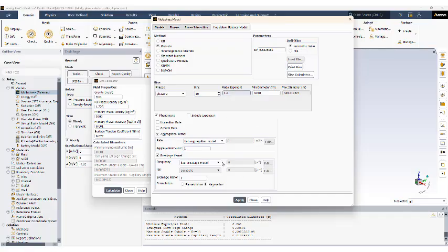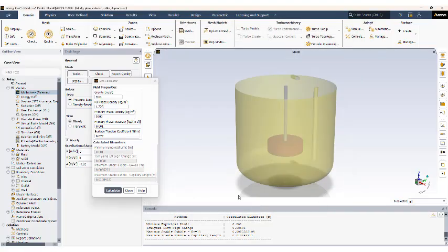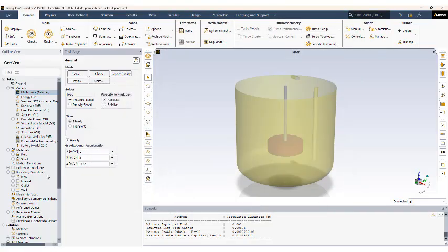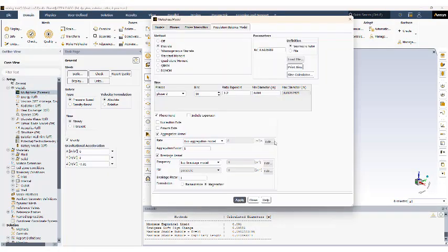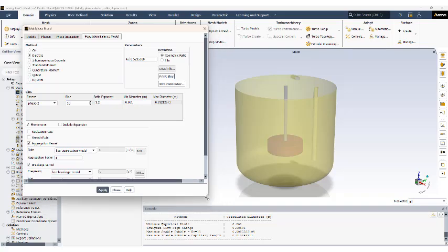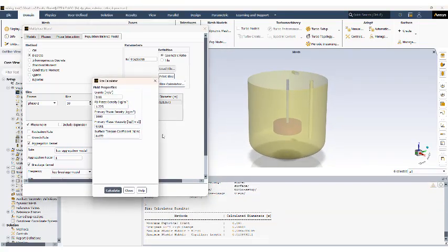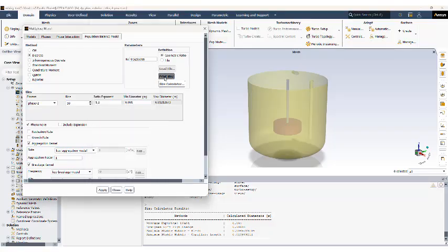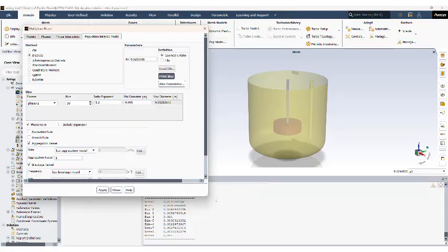So once all of this is set, we can click apply and then close, and then I can close this as well. I should actually go back there. I just want to mention something that's quite important when setting the bins. You can verify the bin size using the print bins. You can verify what are the sizes of each specific bin of particle that you're evaluating.